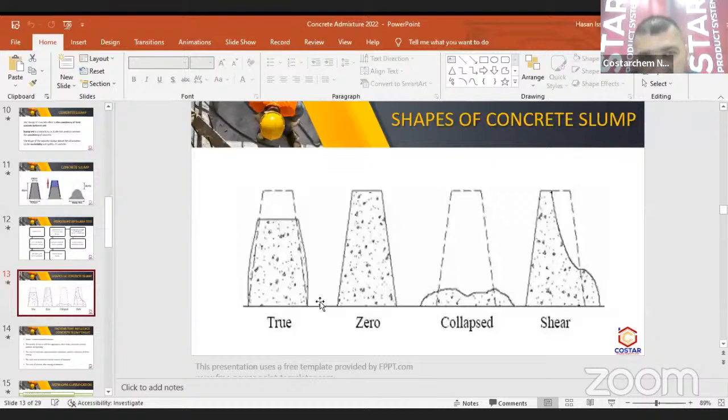A true slump is very, very bad in placing, very bad in transporting, and definitely. I mean, when you want to place it in the foundation or for instance, any element of concrete, a beam or a column, you have to use a lot of vibration. And also, again, this will go into the hand of the worker at site. Experienced workers will be appreciated. However, if not, it will vibrate the concrete to the extent of segregation, and again, the structure is jeopardized. Your durability factor is jeopardized.